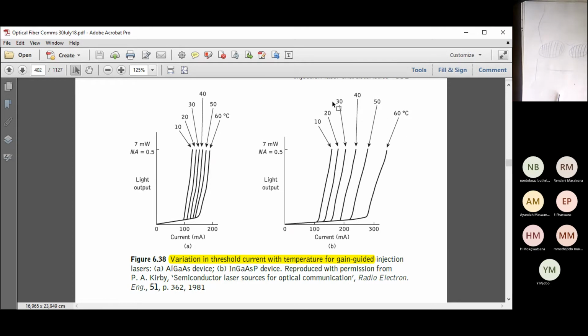And these different temperatures give different currents, which gives a lot of problems with lasers, and not everyone can understand and work with a laser diode. It's very difficult because you must watch the temperature, you must measure it as well, and you must have a temperature controlled fan to fix this current to 200 milliampere.